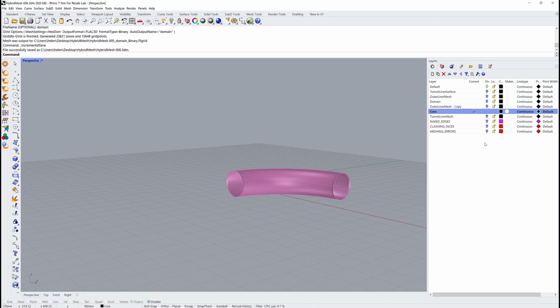The tunnel core mesh will be unstructured but conformal to the liner. In order to keep the conformity between the meshes, the caps of the core need to be re-meshed. The liner's surface mesh will not be affected and acts as the hard edge to the core, to make sure the unstructured core mesh is conformal with the structured liner when generating the volume mesh.